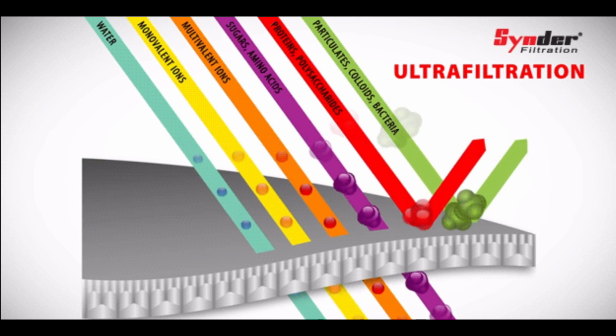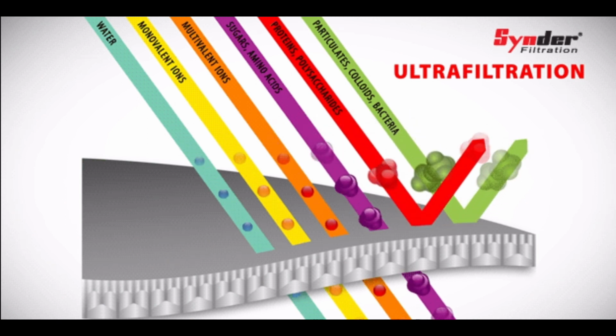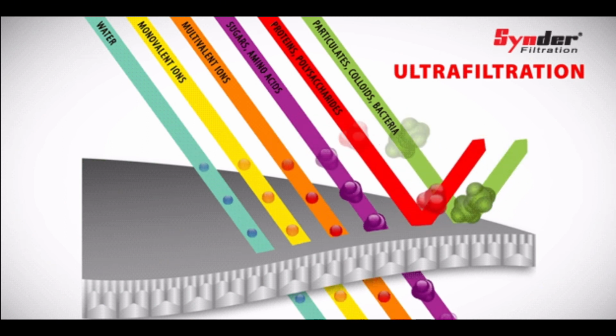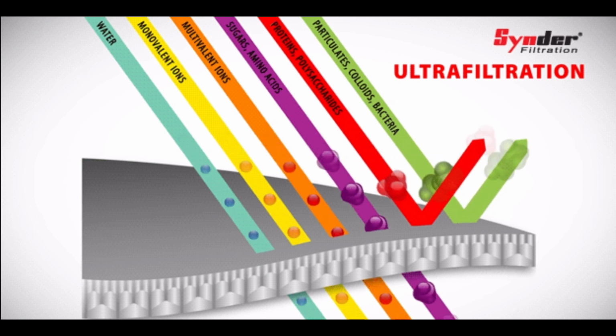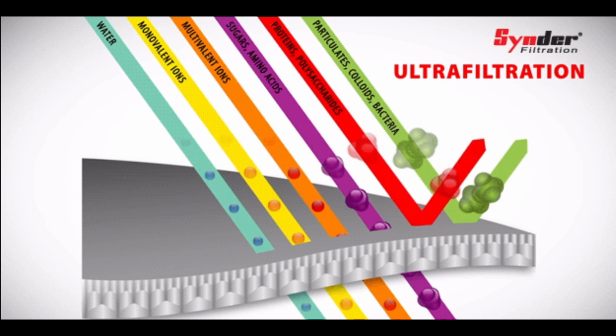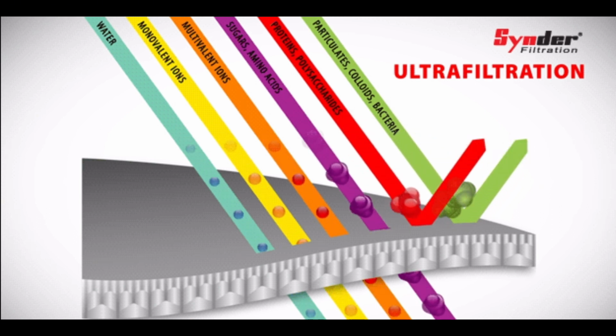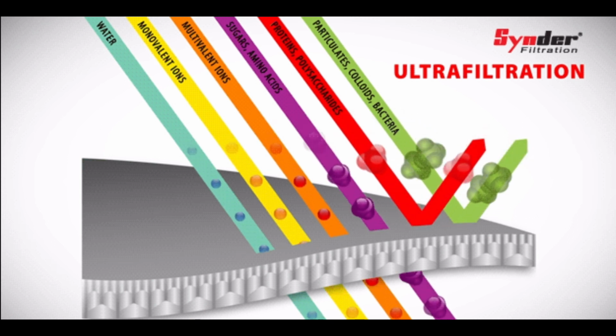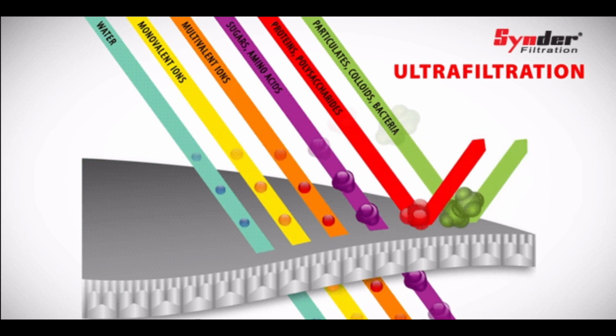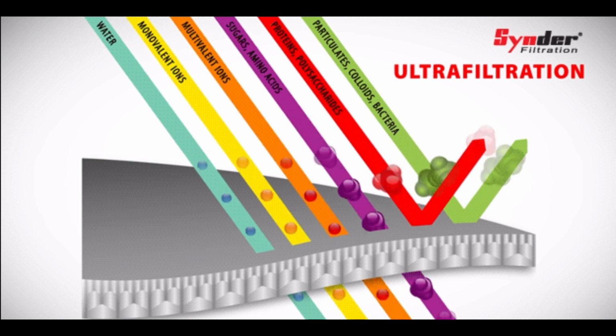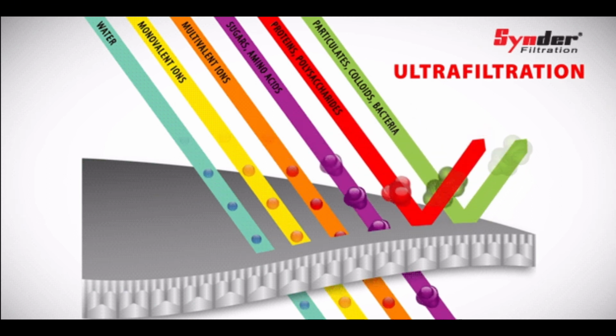as calcium and magnesium. This is why water that is treated by reverse osmosis benefits by going through a magnesium and calcium mineral bed. This adds calcium and magnesium to the water while also increasing the pH and decreasing the corrosive potential of the water. Corrosive water may leach lead and copper from distribution system and household water pipes.